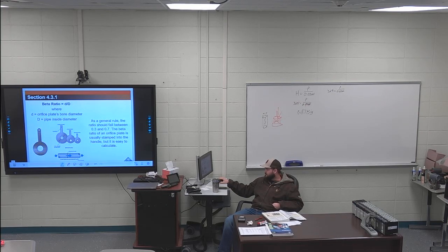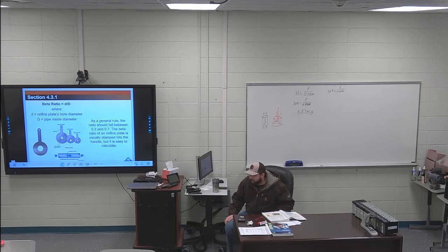Based on the size of the pipe, the orifice, and the math, you can determine a flow. It's very simple, but there's a lot of math that goes into it. But we're never having to do the math, because the square root extractors are built into the differential pressure meters. Does that make sense? You are creating a known disturbance, and based on that, you are determining the flow, which is how most flow meters work.